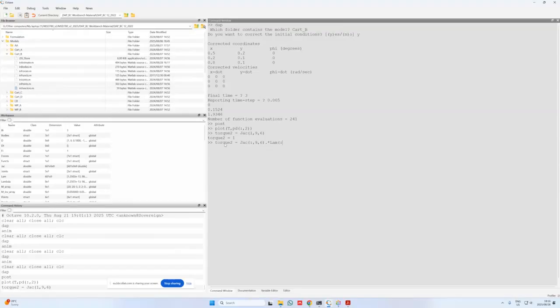For all of the time steps, once again, comma, and now I just need to remind myself that for a Lagrange multiplier, I'm working with 601 by 9, so that is the number of time steps by the number of constraints that I have. I'm considering constraint 9 again, so I simply type in 9 over here. And if you want to double check your method, you can make sure that the second element of the Jacobian always matches the second element that I specify for the Lagrange multiplier. So both of them are 9 in this case, so that's fine.